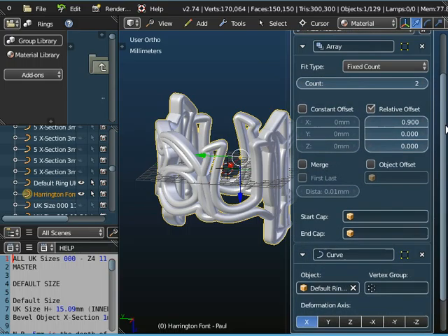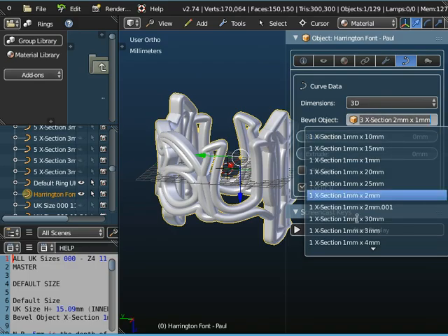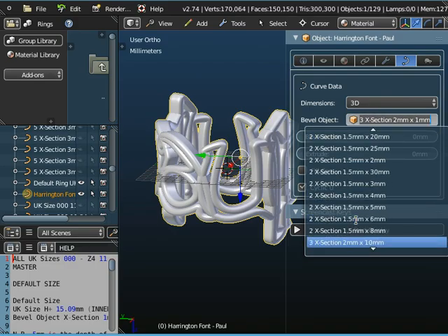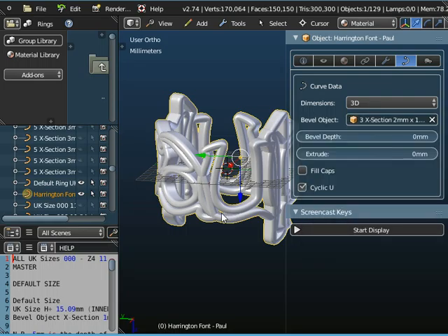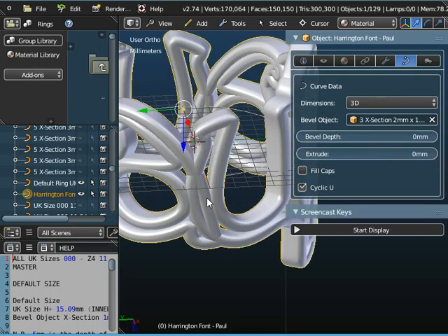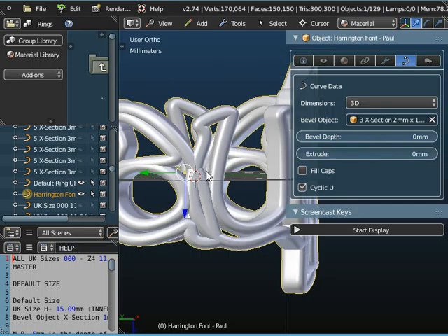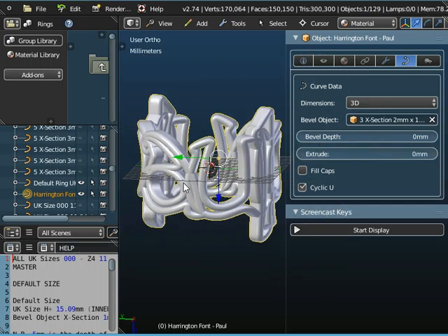And it's 3D printable essentially because we've used a curve here, and we've got a 2x1 cross section which guarantees some thickness to our object, and using curves means that Netfabb will sort it all out for us and make it a printable object. So that's a quick, simple method, 7 minutes to create your own personalised ring.